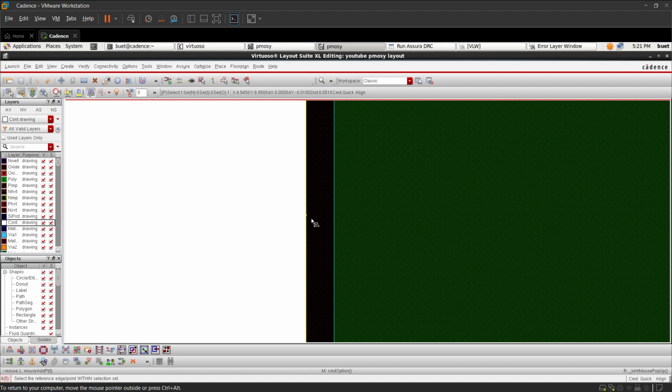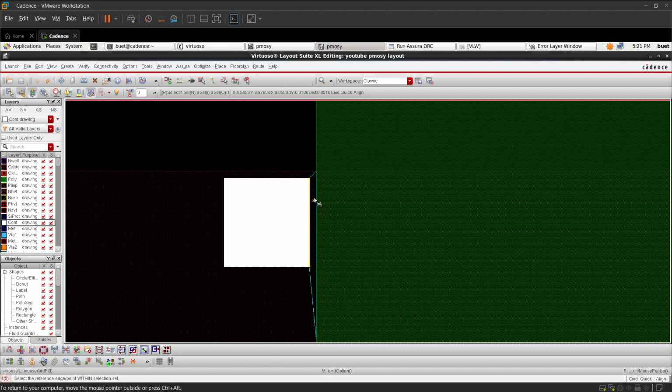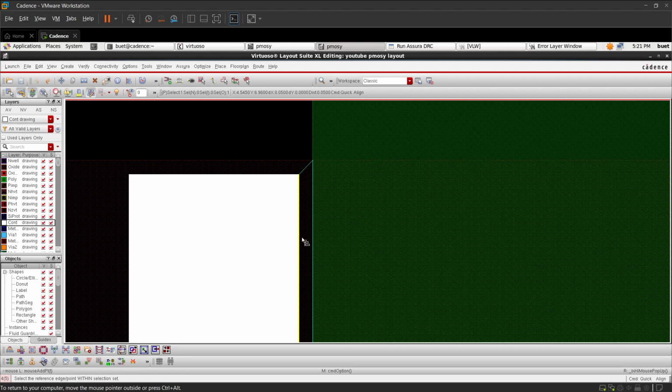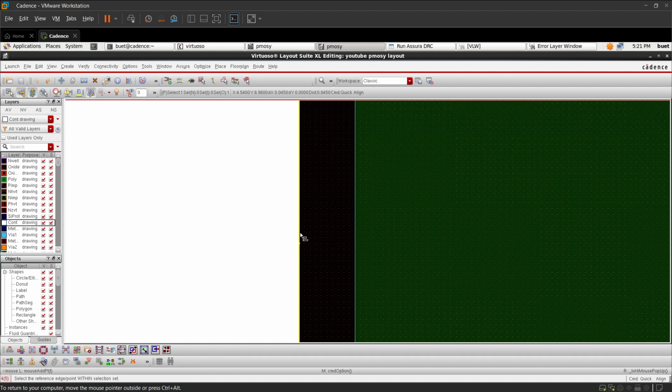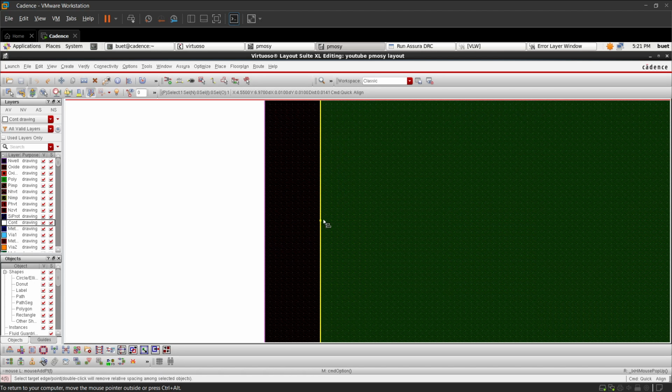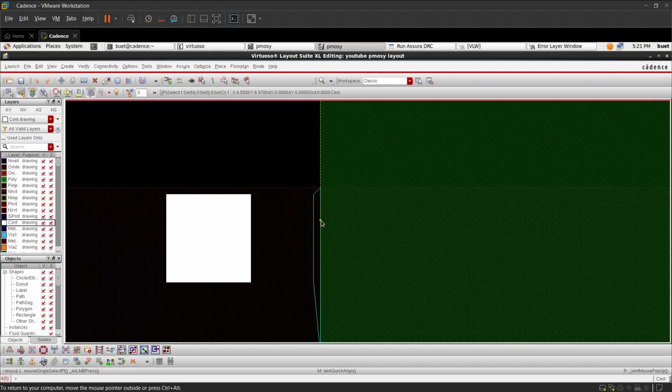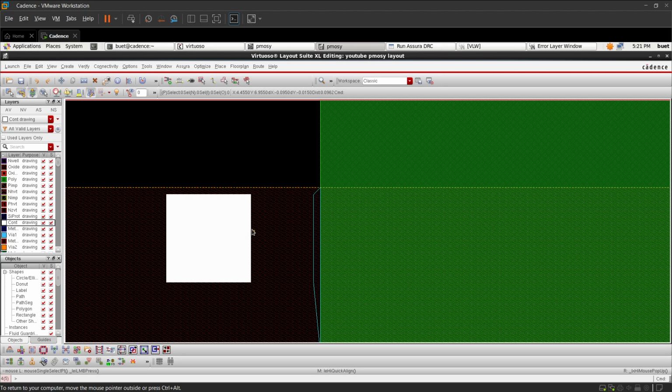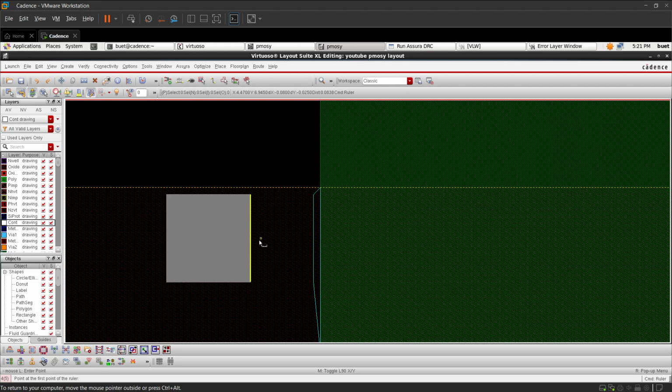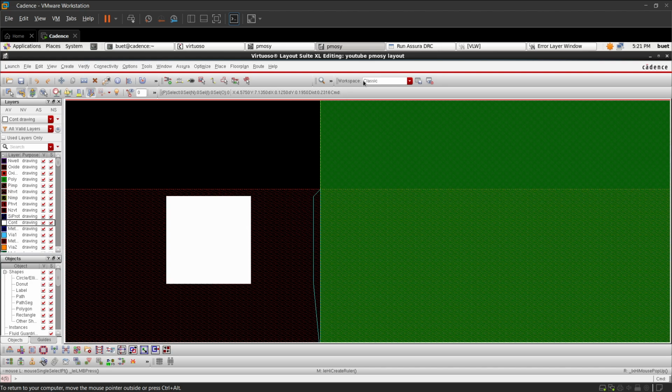And right now you just select the edge of the component you are supposed to move. Just select the edge, with what reference you are supposed to move it. It should be with the gate edge. So as you can see, right now the spacing between the gate edge and contact edge is 0.1. Okay, just escape. The next error is related to what the spacing should be from our oxide edge to the contact edge.